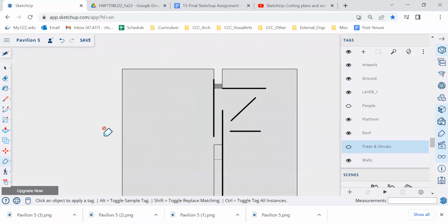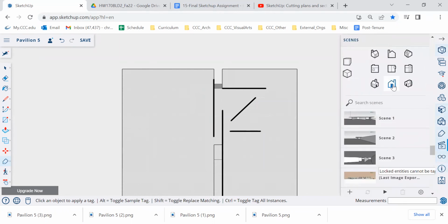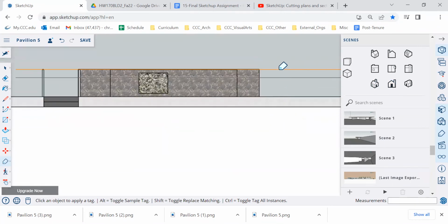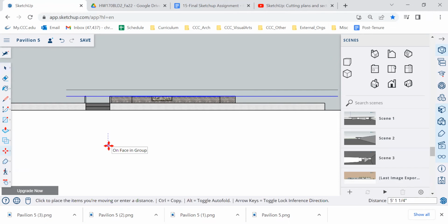Okay, now you don't see anything from this view. To visualize where this is, you can go to one of the elevations. All right, and when I zoom in here, I can see this orange line is now visible. That is the section plane. Now, as I mentioned, typically in a floor plan, that horizontal plane would be about 4 feet above the ground. My walls are 8 feet. So if I was to move it down 4 feet, you can see as I go through the move command that it's starting to drop.